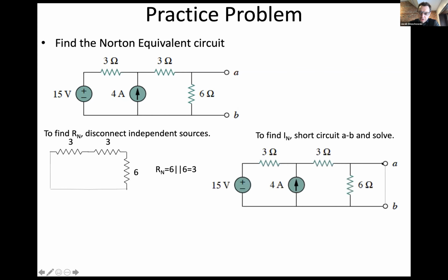Okay. So when you short circuit A and B, you get this equation. So now what happens to the 6 ohm resistor in this picture? It gets bypassed. That's right, it gets bypassed. So you can just ignore it. So we can just do a very simple nodal analysis with one node V. So what is the value of the current from here to here, expressed in terms of voltages and resistors?